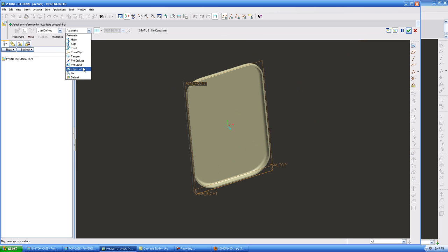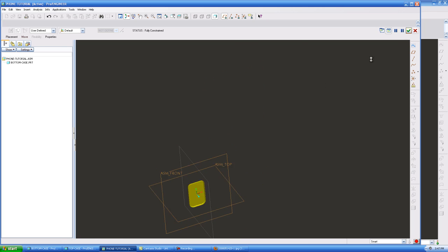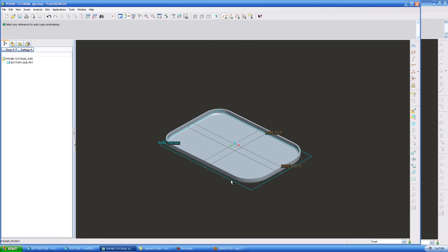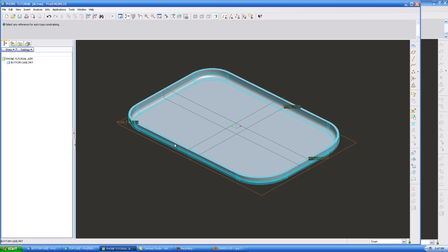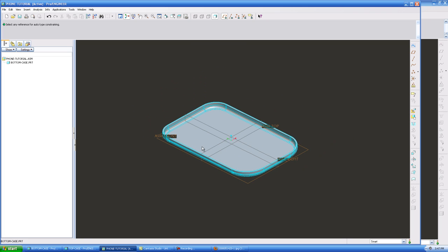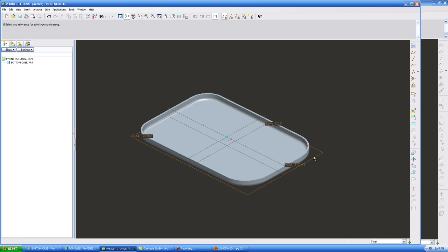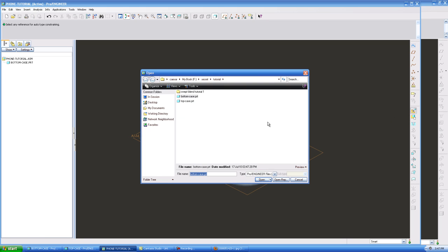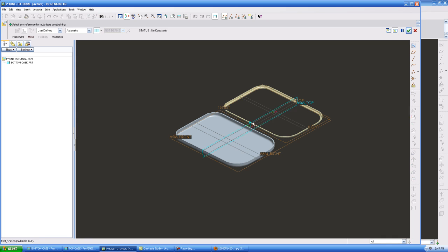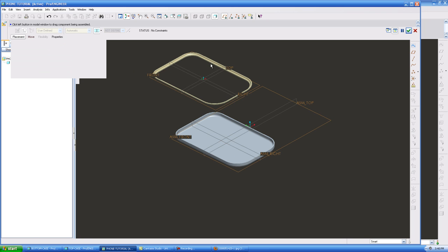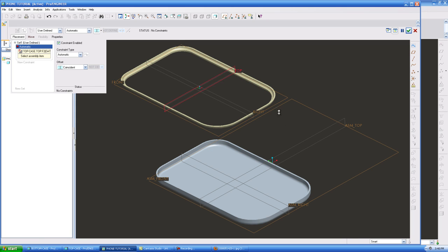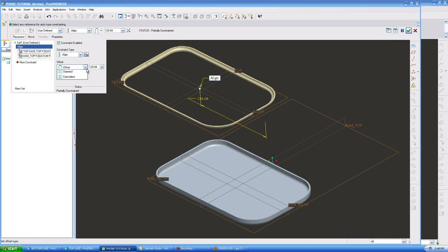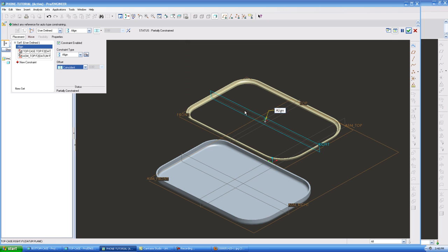But because I'm putting it in at default location, it centers it. So now you can see the only planes that are visible are the assembly planes, which is all I want to see anyways. Otherwise, your front, top, and right from the bottom of the case are going to be overlaid on the assembly top, front, and right. So it saves confusion down the road if you start doing things in an orderly fashion from the start. It's just little things like that as you'll go on down the road that you'll start to notice that you would like people to start doing when you have to work on their models.